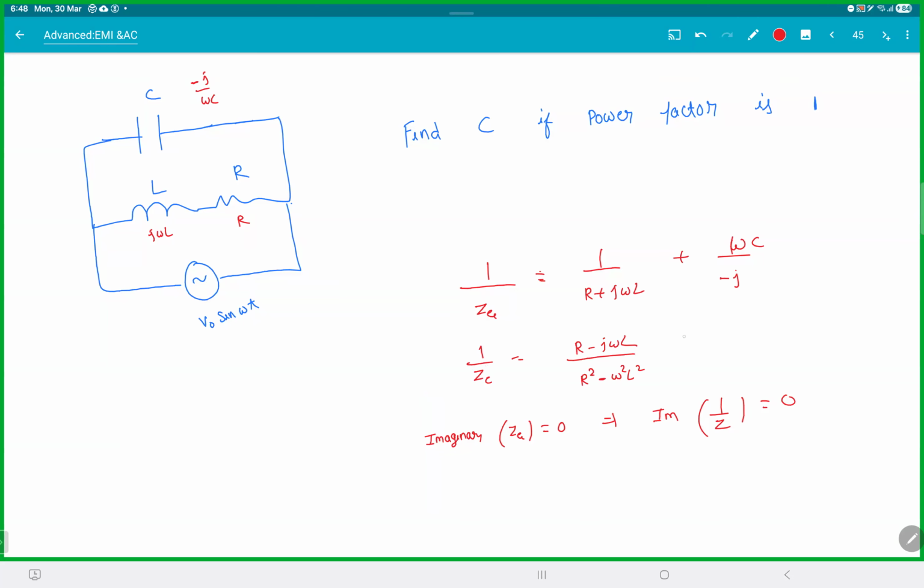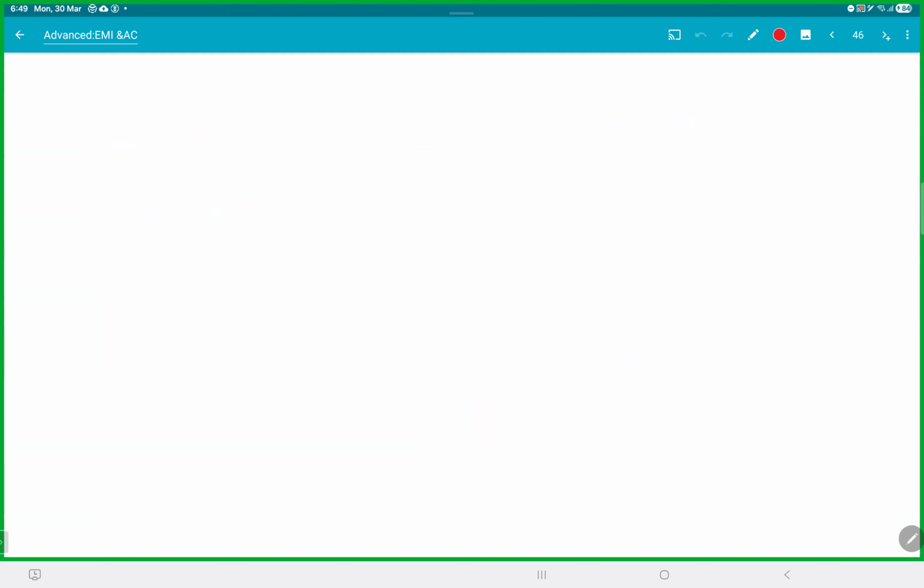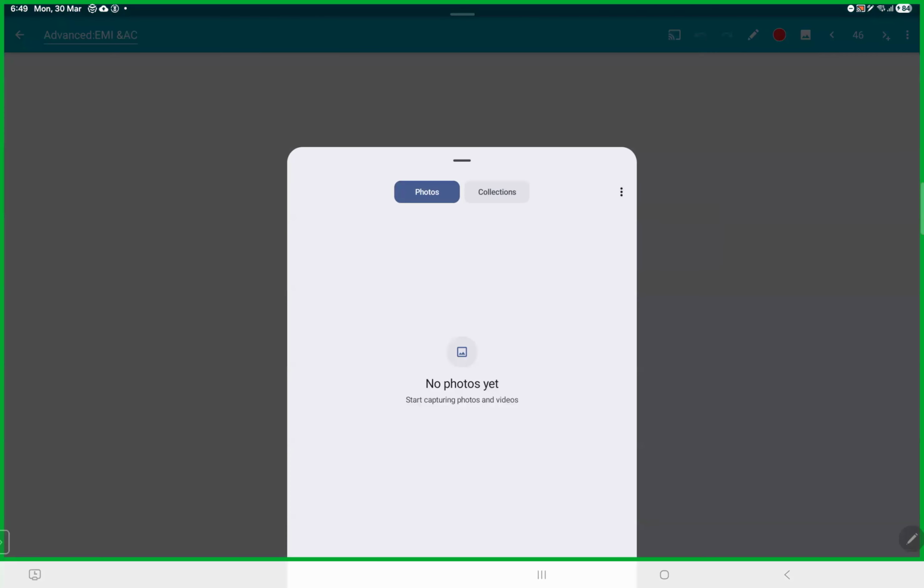And this one would be multiplied by minus j and minus j, minus j omega c something. You can simplify; I'll leave it to you. You guys are better at complex numbers. Clear with this? Or you can just flip it and do whatever you want. So basically get Z equivalent and finish it off. The complex approach is the easiest way to do it. You can handle that with phasors also, but this is preferable.